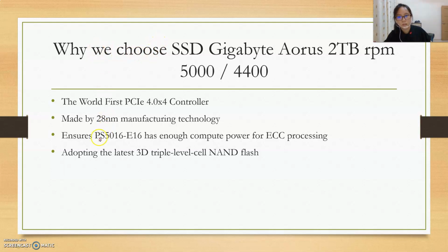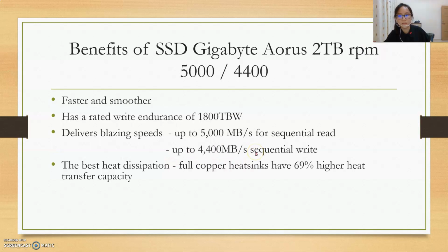Its Phison PS5016-E16 has enough computing power for ECC processing, and is adopting the Toshiba 3D triple-level cell NAND flash. And the benefit of this SSD is that it is faster and smoother, and it has a read-write endurance of 1800 TBW.